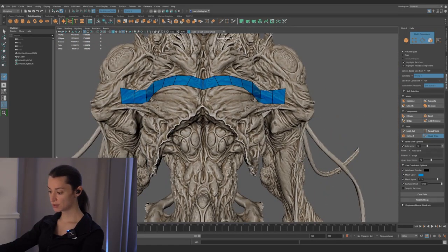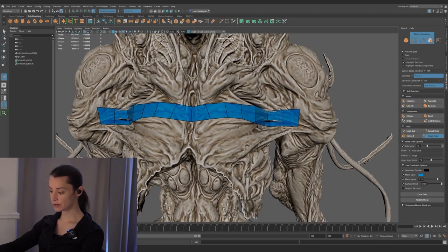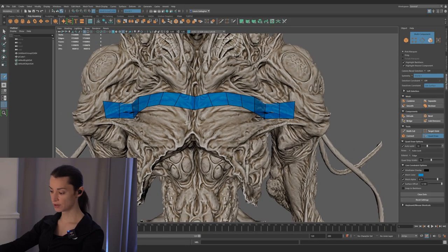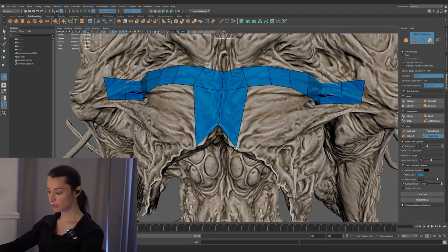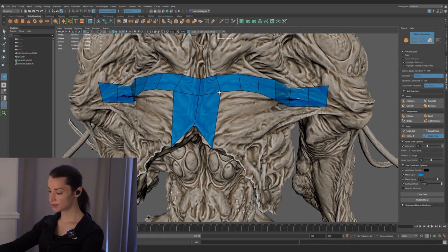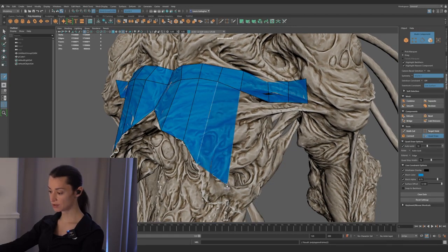So now what we want to start to do is really just to start to extrude a bunch of these different edges to really fill in the whole area of the pectoralis with different edge loops, different quads. We can start from anywhere that we want here, starting from the center line kind of made a bit of sense to me. And here I'm extruding these vertices down, once again by holding down Tab and then simply clicking on those vertices.